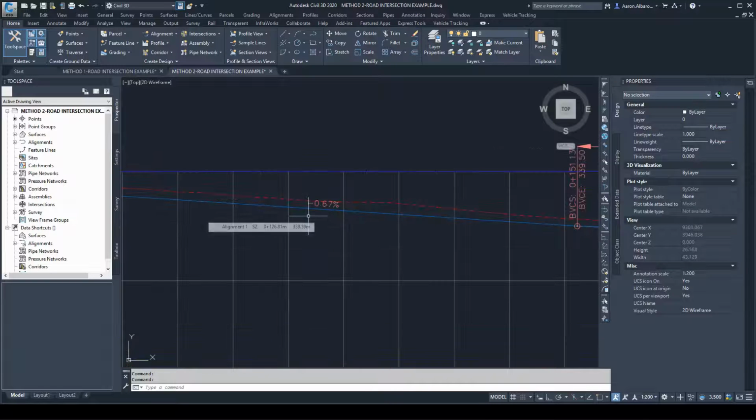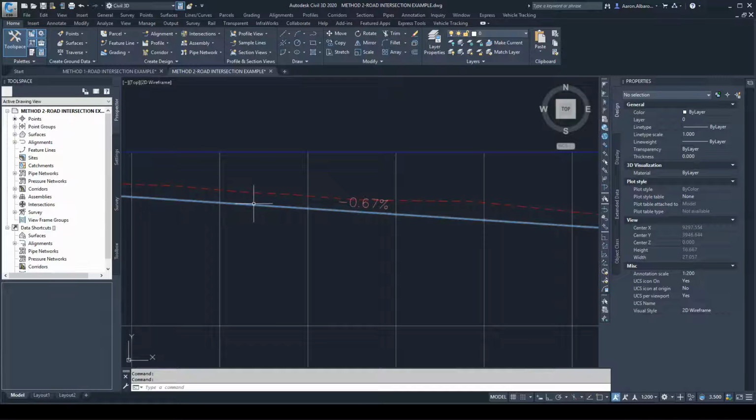That having been said, if we are designing a rural design or a road design for a highway, it will be the opposite. We should eliminate the amount of water coming from the surrounding grounds into our road. In other words, if we have our road in a cut arrangement like this, where the road is below the surrounding grounds, we should provide some kind of drainage channels, which we'll call table drains, on both sides of the road to allow the water to be drained.